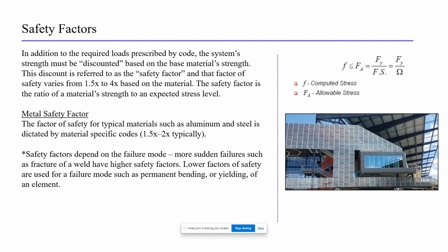Besides that, the factor of safety, if you will, the load factor they use in IBC is 2.5. That's usually higher than what's used in the material standards, as is explained here, that 1.5 to 2. And more importantly, it can become quite expensive. It's not required for most demountable equipment, but if it's required by the ownership or the GC or the architect, just for peace of mind, it should be discussed with the design team and written in the specifications properly.